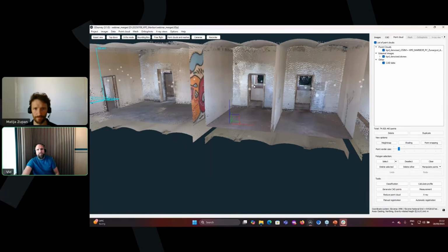For the second part, if you have issues with SLAM drift, what you can do is add in ground control points to eliminate that drift if that's necessary. That's one way, or the other way is to make sure that you get RTK GPS every here and there, and that will also eliminate the drift. If you fail at both of those, I'm afraid there's not much you can do. So make sure you have some backup in GCPs, and that you go outside to get an RTK signal. This is your best recipe to not drift.